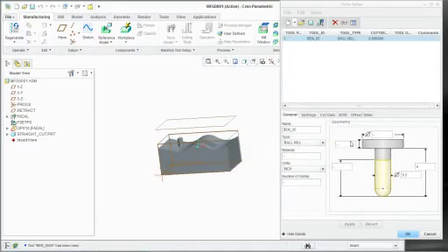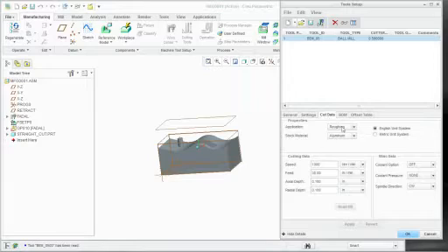Okay. Now, this stuff is pretty straightforward. Essentially, you have an edited tool that has a standard shape, and you change the shape. But what I find is a lot of customers don't fill out this information right here in the cut data. What this allows me to do is regulate speed, feed, depth of cut, and step over based off of a material and an application. And then what I can do is fill this information out based on these two ideas and the tool, put in my cut data, and then save that to that .xml.